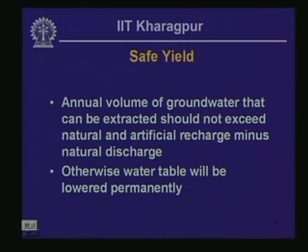In other words, safe yield is that volume of groundwater which can be extracted without permanently lowering the water table, and so the quantity should not exceed the natural and artificial recharge that the aquifer can have over the year minus the natural discharge from the aquifer.